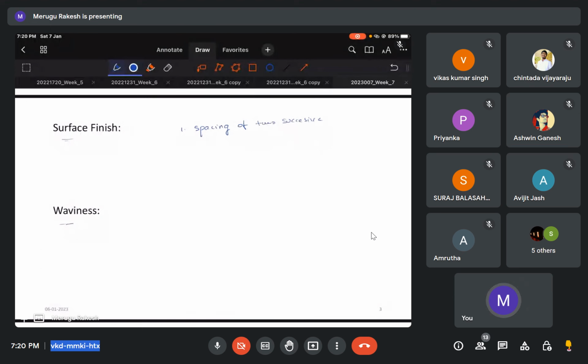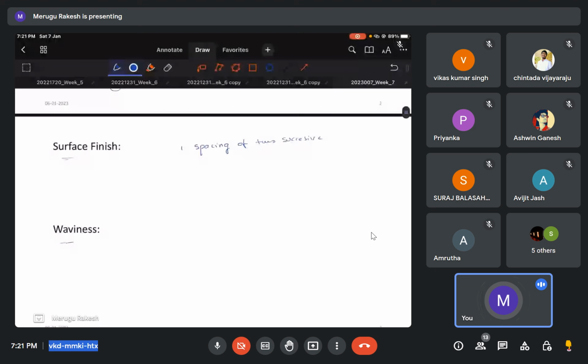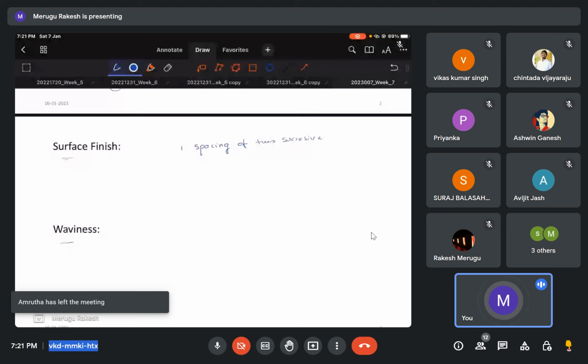Oh yeah, that's true. So whatever is related to tool chatter or these inclusions, as someone pointed out, will decide the surface finish factor. Whereas machine vibrations, or any intermittent machining, or any jerk during the machining process related to the machine, give rise to waviness. So you can see the scale basically. As someone pointed, this micro scale is related to surface finish, whereas this macro scale is related to waviness.